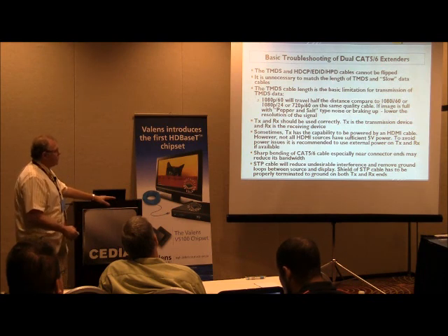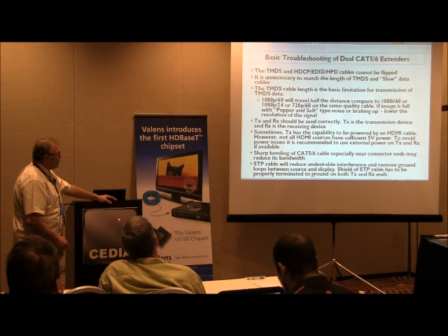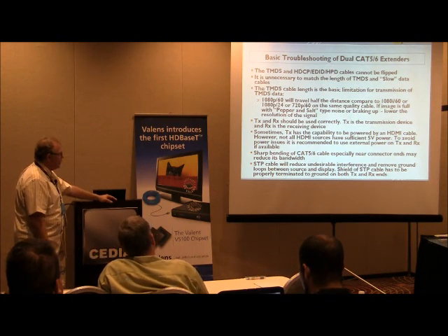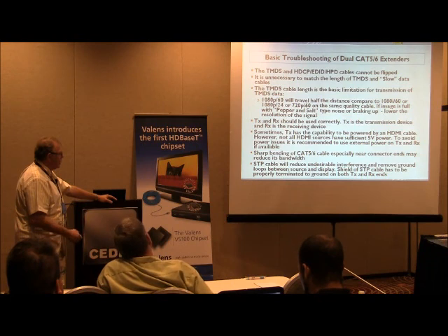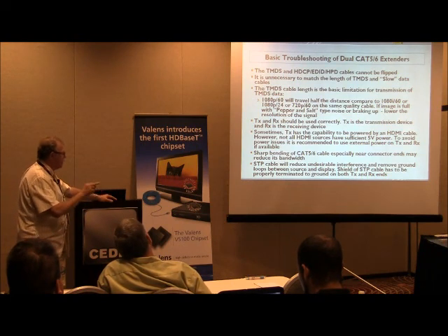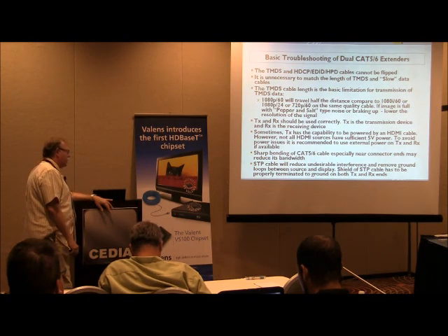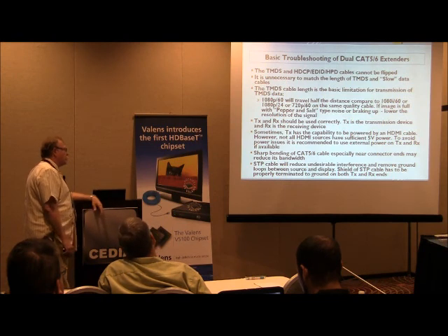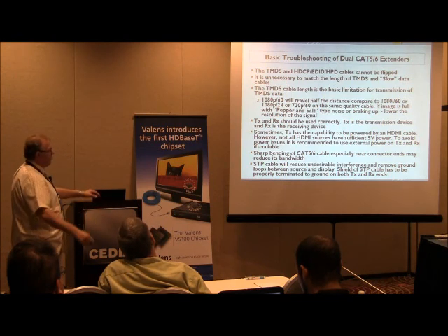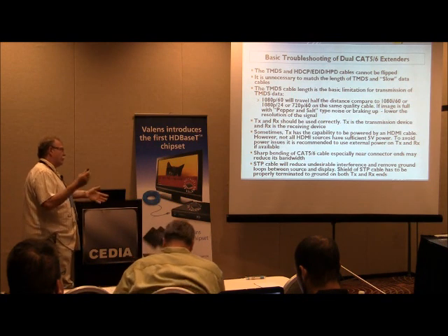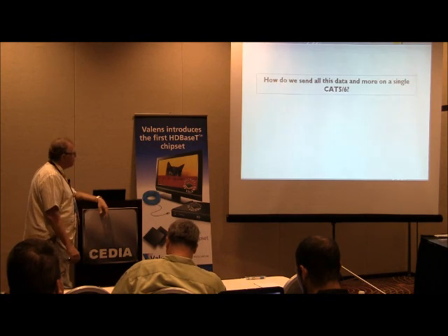In basic troubleshooting of this device, there's not much difference from what we just talked about for HDMI cables. The reason is that it's the same type of data and the same type of sensing, looking for pepper and salt. I recommend you don't reverse TX or RX, and don't reverse data lines and video lines. Basically straightforward techniques, no sharp bending, and using shielded Cat6 always helps because it avoids interference from outside and makes the ground common on both ends, which unifies the ground instead of ground interference and ground loops that may be present over long distances.